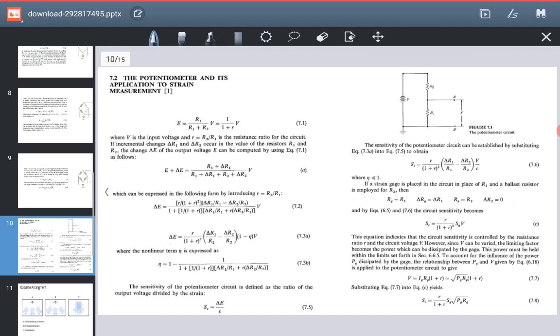the potential difference changes, so our R1 will be replaced by R1 dash, which is the new R1, and this will be replaced by R1 dash divided by R2 dash. So R1 dash will be equal to delta R1 plus R1. Okay, so this is the new resistance. So we simply put this in this equation. This equation after the change in resistance will be this. Okay. Now,